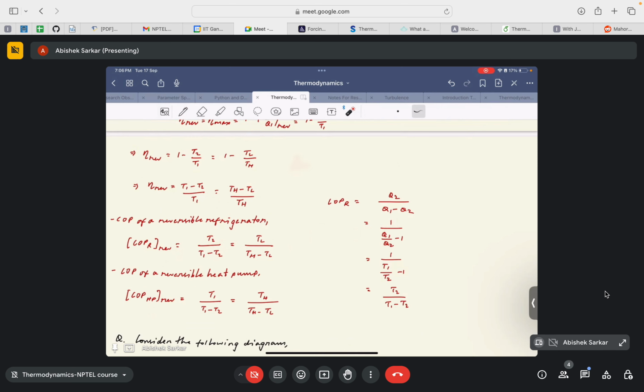Okay, in order to trick you, the temperature in the questions might be given in degrees Celsius. But to recall all these temperatures that you deal with while finding the efficiency or COP, you need to take those temperatures on the absolute scale. Because, as Anil rightly mentioned about the numerator, why? Because in the case of the denominator, since it's a temperature difference, even if you take it in Celsius or Kelvin, it doesn't matter, the difference will remain constant, right?